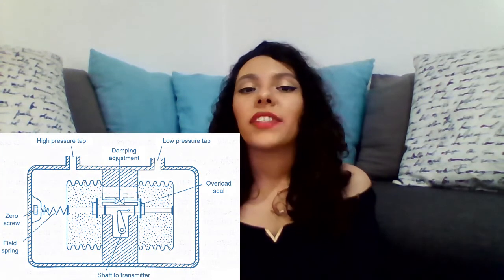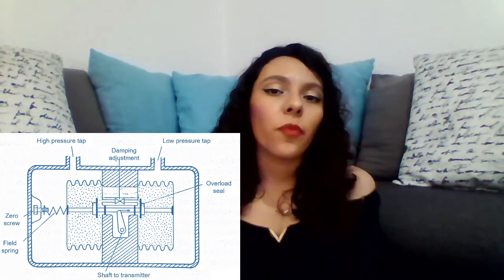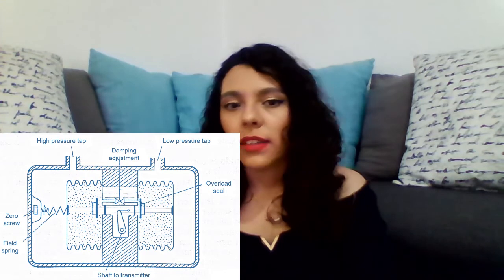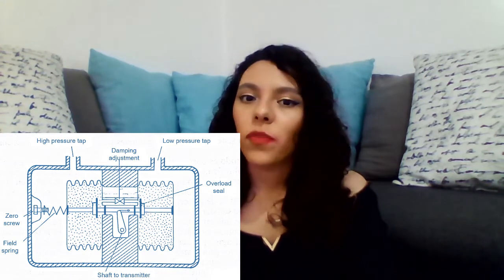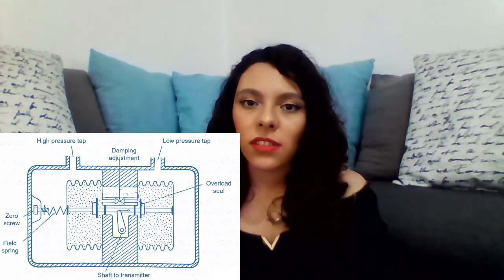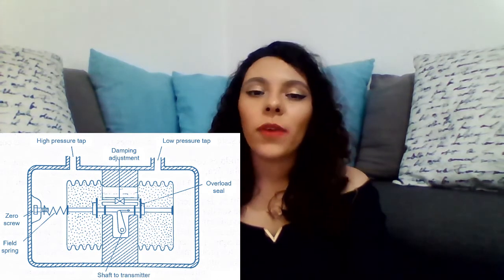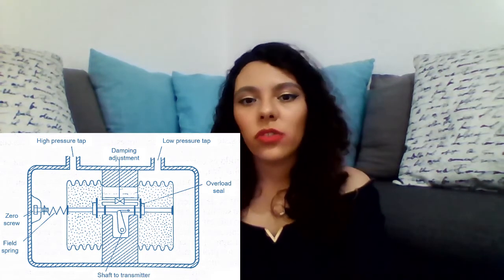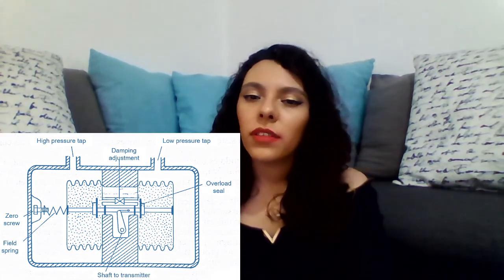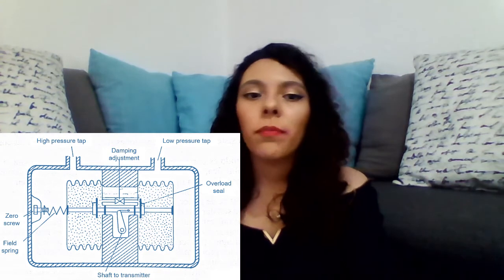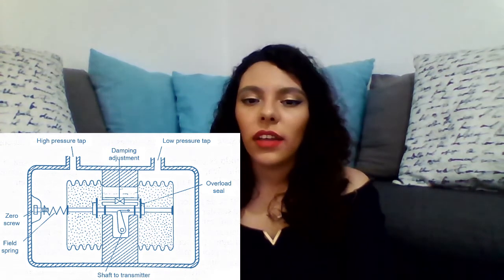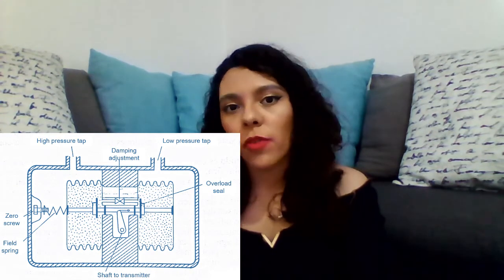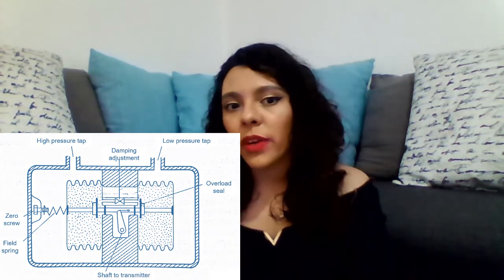The bellows type has a chamber for high pressure and another for low pressure. The high pressure compresses the bellows, which drives the joint lever, the cable, and the outer shaft, whose movement acts on the pneumatic or electronic transducer. A margin spring allows for various differential pressure ranges. Protection against overloads is ensured by two seal rings that hermetically close the passage of the filling liquid from one bellows to another and prevent its destruction by incorrect operations. It also has an anti-pulse flow valve that restricts the flow of filling liquid between the bellows.